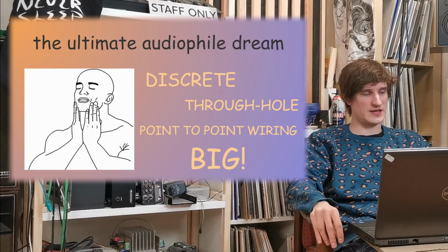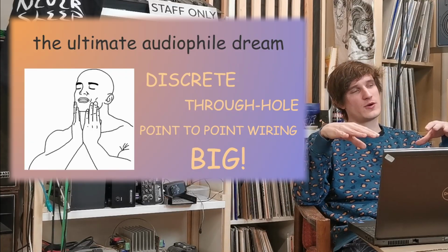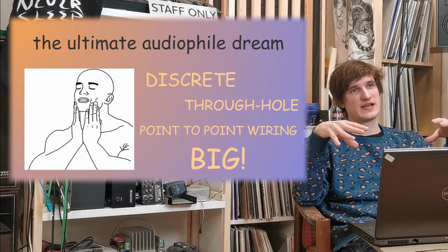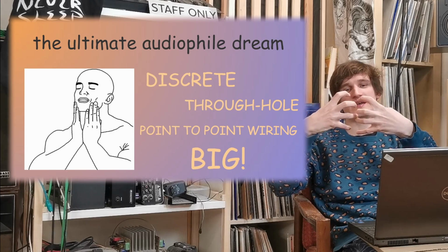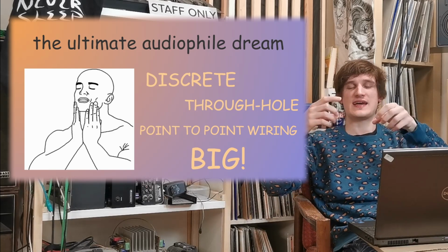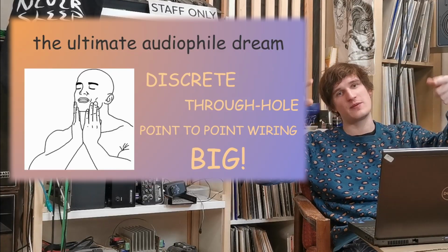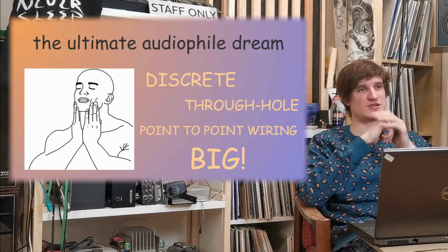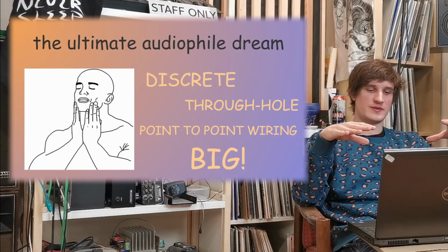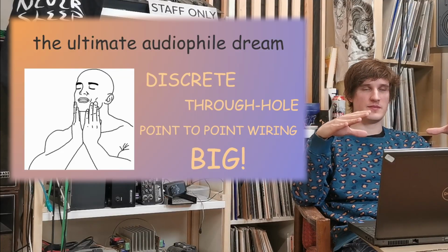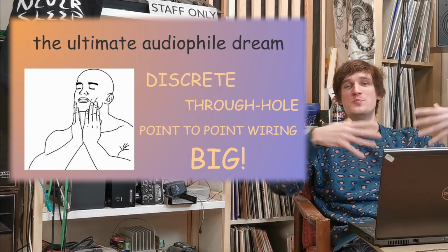So point-to-point wiring doesn't necessarily bring some benefits. For example, one of the benefits is that when you have a mechanical connector, through time the contact may get a bit worse, and when you wire something point-to-point without a connector, it can be more reliable through the years. But this is not really necessary.